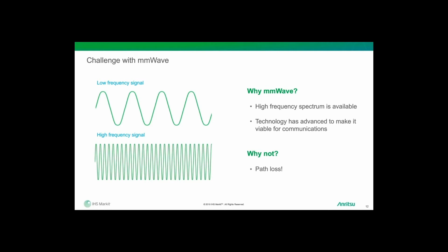So that's actually recently led the FCC in the U.S. to reassign the 2.5 gigahertz band and announce auctions for that. It's also important in millimeter wave because with this need for wide bandwidth, it's really rare across the world to see any of the countries auction off more than 100 megahertz of contiguous bandwidth for a single carrier. Like Richard mentioned, according to the 3GPP defined opportunities for 5G, you can have a single carrier up to 400 megahertz. You can also have aggregated carriers, either 4x100 or 8x100, to give you that full bandwidth, especially when we're talking about broadband internet into a neighborhood.